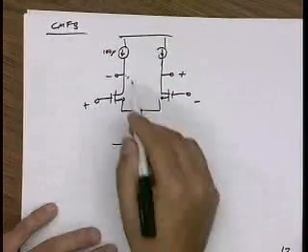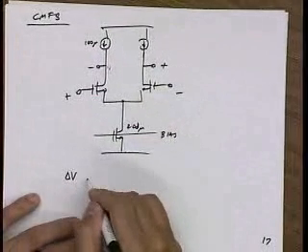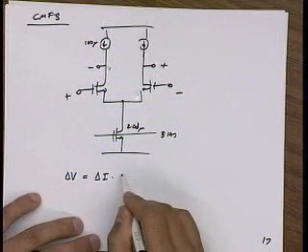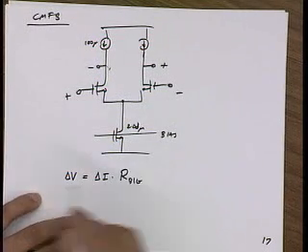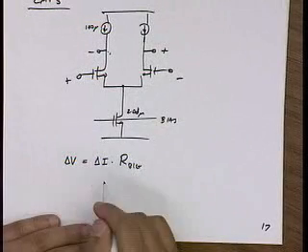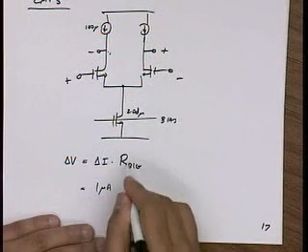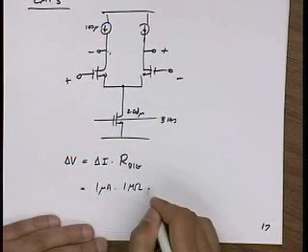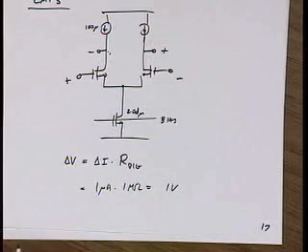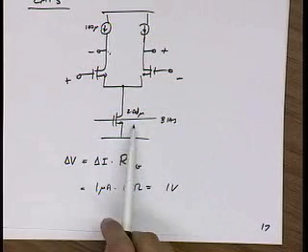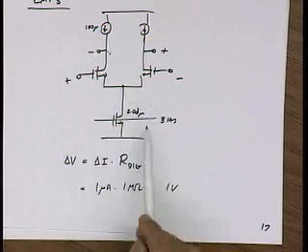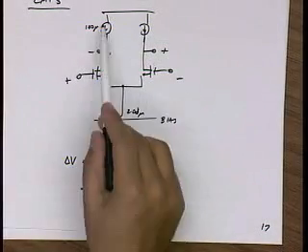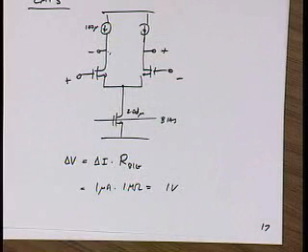And the idea is that the voltage out here, delta V, is very sensitive to delta I because you have such a large output resistance. So for instance, in this case, if I have just a microamp, and let's say R big is a mega ohm, then delta V is a volt. So just 1 microamp, which is 1 part in 200, 0.5%, will totally mess this up. So if I don't have 0.5% matching, I'm going to mess this up.